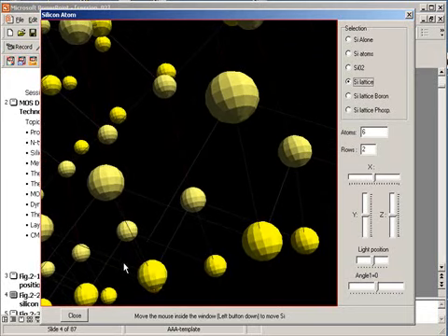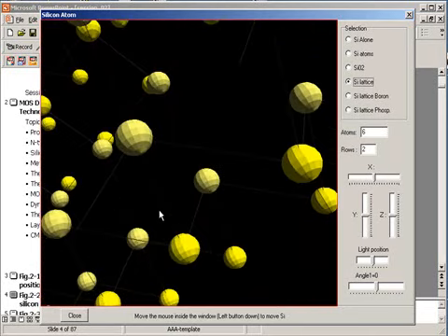Since they have 5 valence electrons, and 4 find room in the lattice, 1 electron is released and participates in electrical conduction. Consequently, phosphorus and arsenic are named electron donors with an N-type symbol, so N-type semiconductor. A very high concentration of donors is called N++.